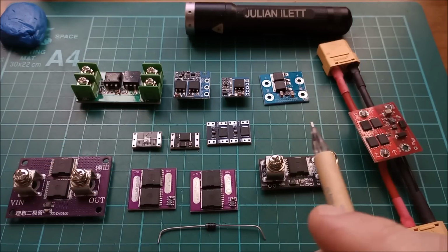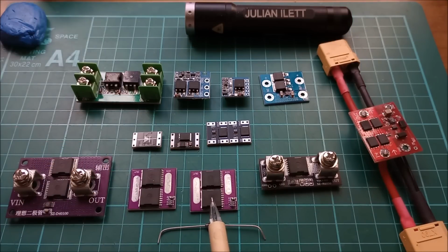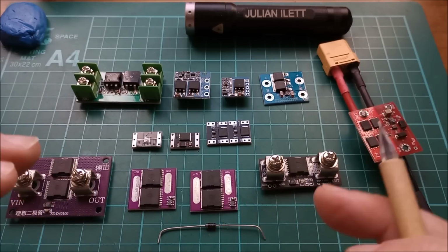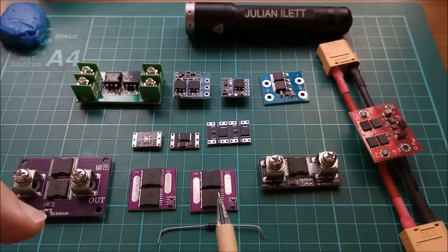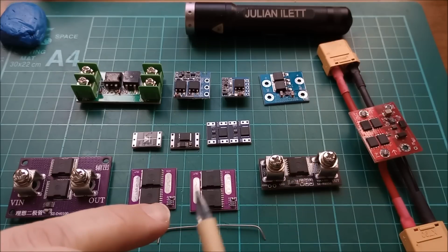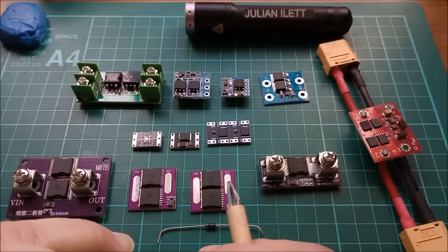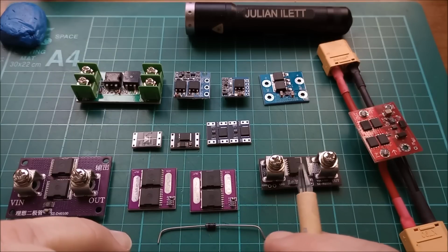So by using MOSFETs, you can initially pass a current through the body diode of the MOSFET, but then if you can have some sort of system which turns the MOSFET on, you can lower the resistance of the conduction channel in the MOSFET, and MOSFETs have a linear voltage and current relationship, so they talk about an on resistance, but the on resistance of these things is very, very low, in some cases less than a milliohm.